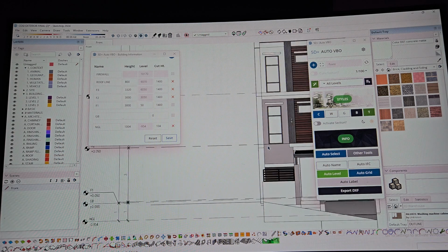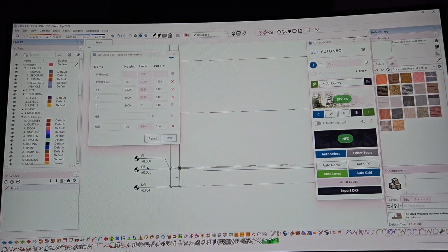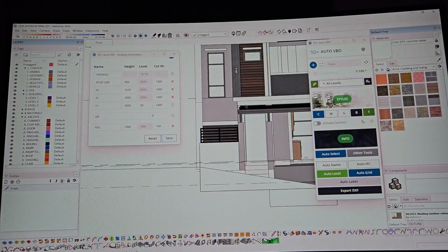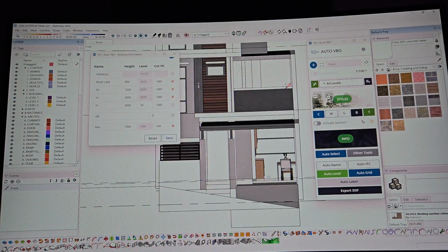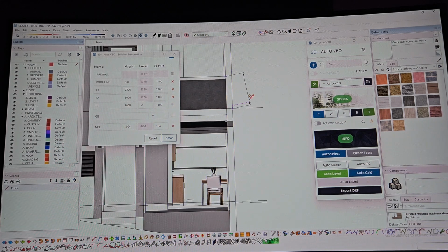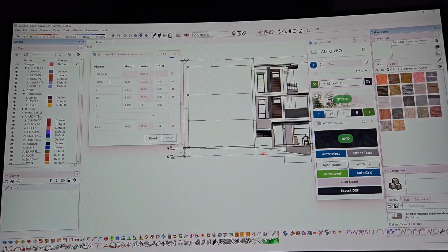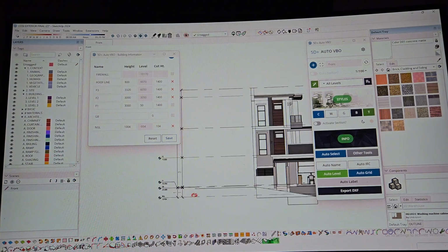To put the grade beam or the top of the beam levels there. But we'll always base it on the finish line so it will not be hard for our doors and windows later on if we are getting a reference like our balconies. We'll base it from the interior finish line instead of the top of the grade beam. That is what was standard being used.